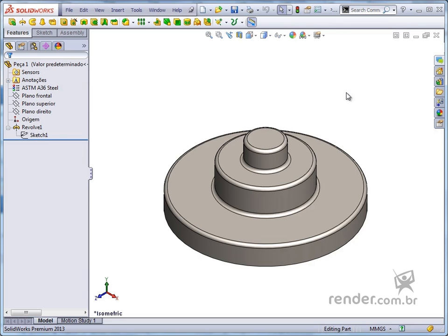There are several important points to consider, for example, modeling a part using the fewest number of features, model by manufacturing sequence, model in such a way as to facilitate subsequent alterations. Anyway, all this must be defined before the start of modeling, allowing us to choose the optimal profile for the beginning of work.